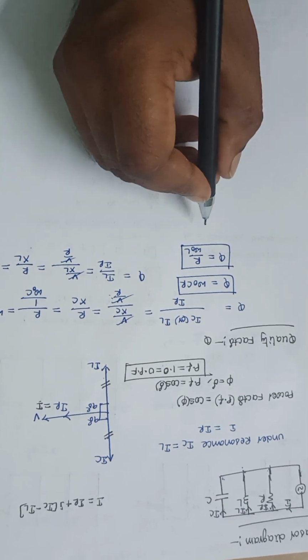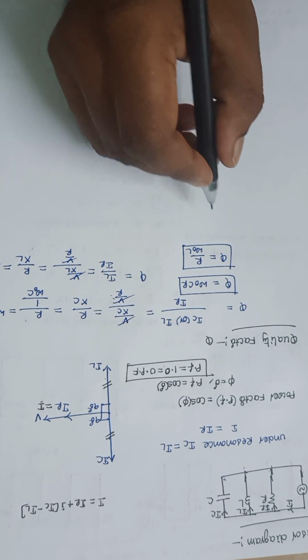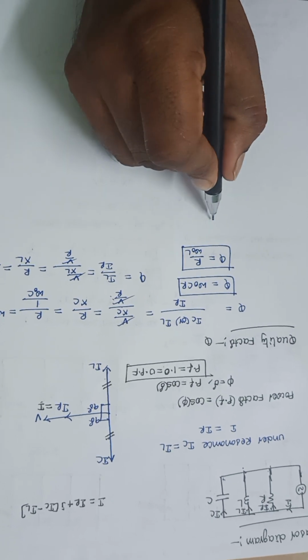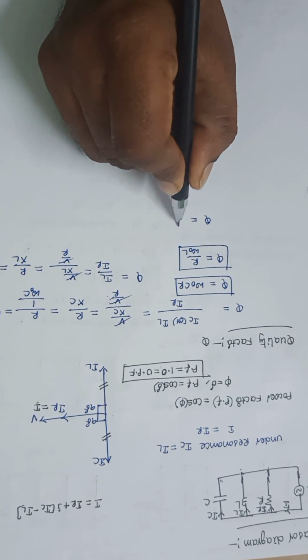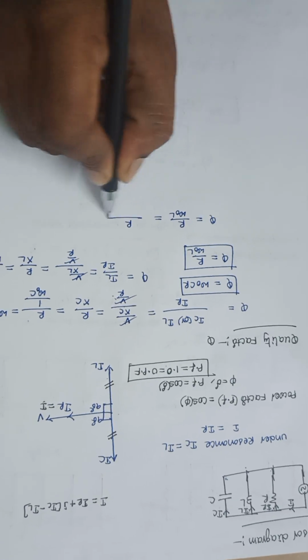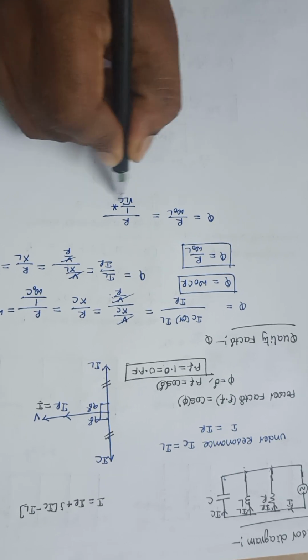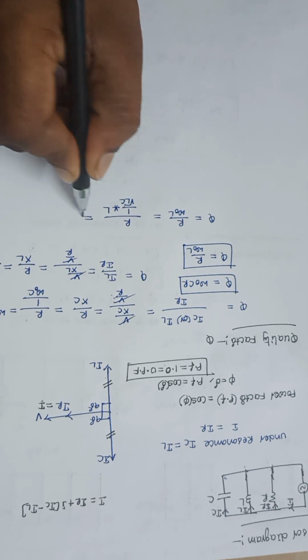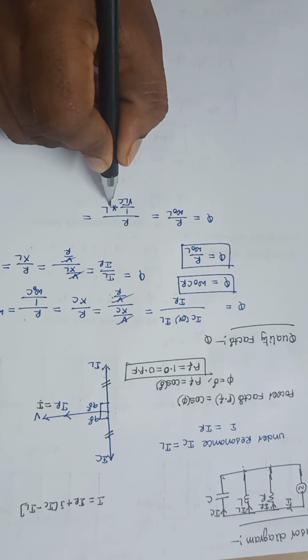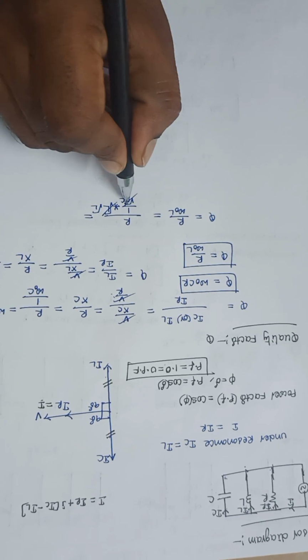Now in terms of R, L and C elements, I am going to find the quality factor. Q is equal to R divided by omega naught L, that is R divided by omega naught, where omega naught is 1 by root LC, the resonance frequency for a parallel RLC circuit, times L. I can write L as root L into root L, so one root L cancels.